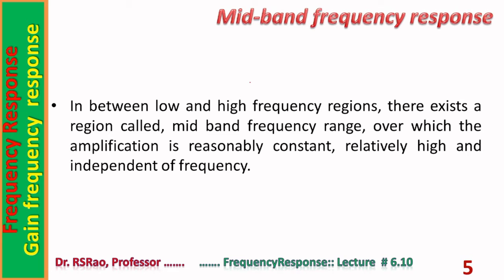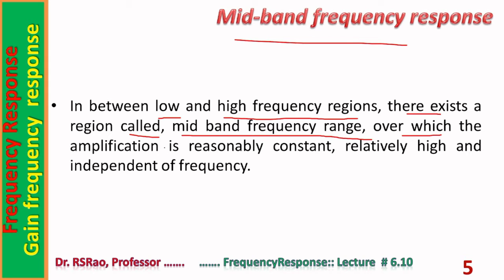Apart from the lower frequency range and upper frequency range, there is another frequency range. It is called the mid-frequency range. In between the low and high frequency regions, there exists a region called the mid-band frequency range, over which the amplification is reasonably constant, relatively high and independent of frequency.